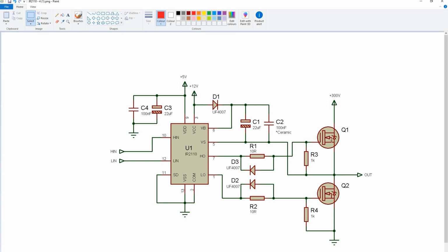So the high side, basically to switch on a MOSFET or an IGBT gate, you need to have the voltage of this one between 5 and 20 volts above your source here. So 5 to 20 volt above here. But how do you get 5 to 20 volt above here?